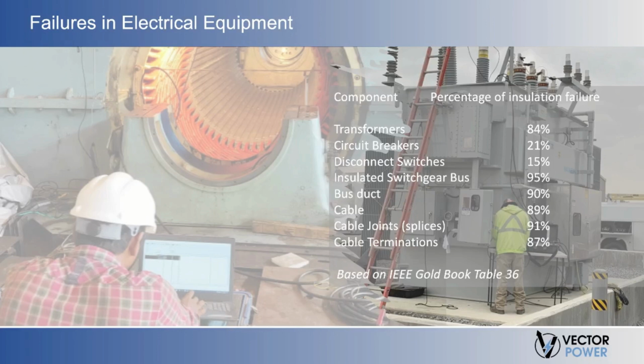Dissipation or power factor testing also makes it possible to detect equipment insulation problems without making an internal visual inspection. The result is a significant decrease in maintenance costs and downtime. This testing is one of the best testing techniques for a predictive and or a preventative maintenance program.